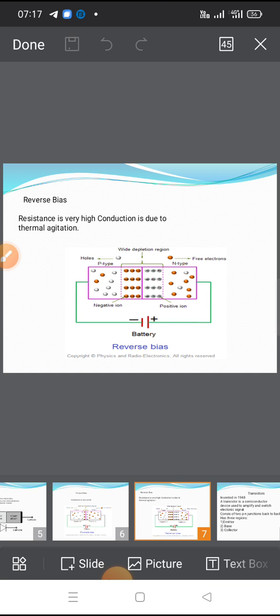In this case, the built-in electric field and the applied electric field are in the same direction. When the two fields are added, the resultant electric field is in the same direction as the built-in electric field, creating a more resistive, thicker depletion region. The depletion region becomes more resistive and thicker if the applied voltage becomes larger.